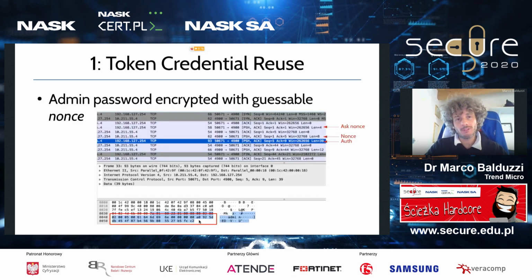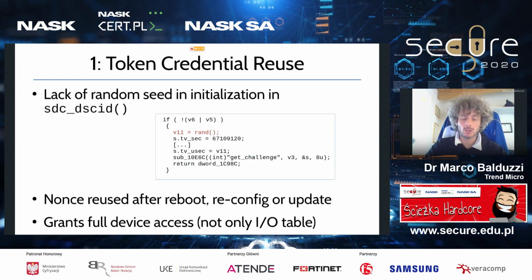So the first problem we found is that the admin password is encrypted with a nonce, so with a random value that is guessable. This is because during the initialization phase of the device, for example after a boot, this v11, which is used in the randomization function of this nonce, does not come with an initialization vector. So it's always the same.